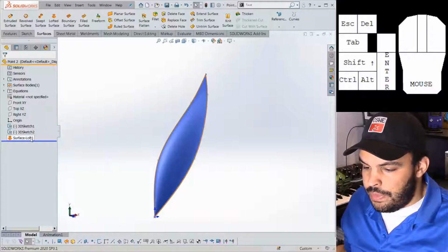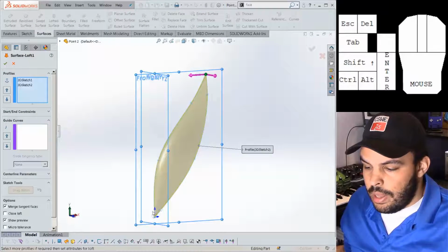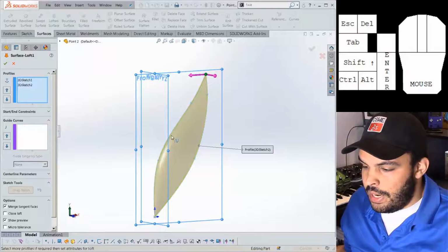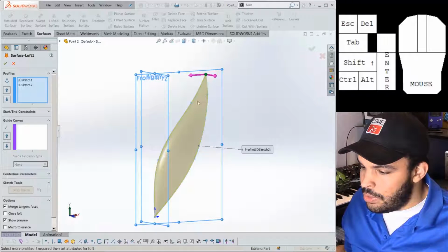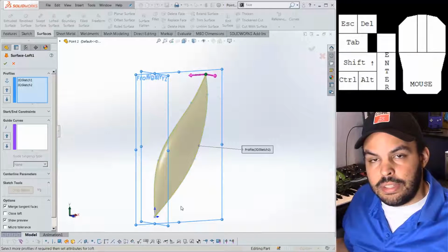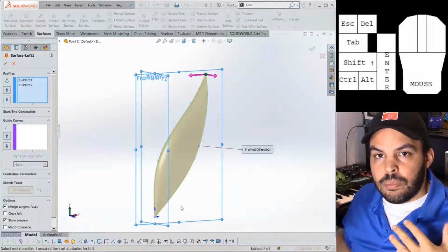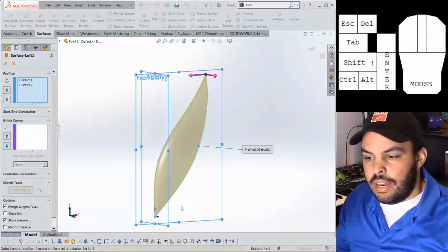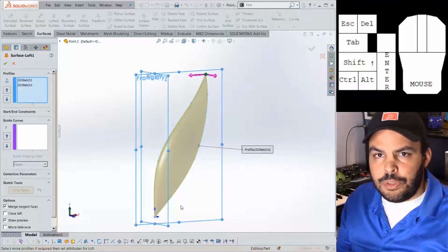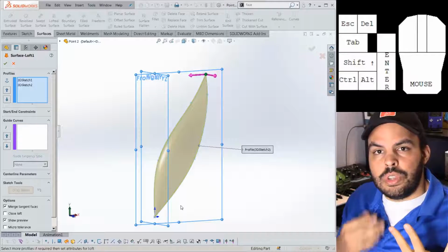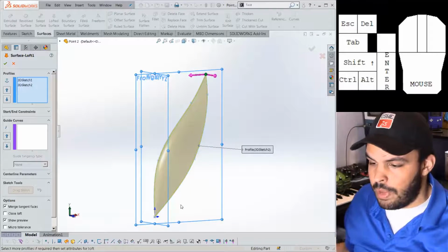So what happens if you use a loft on that, the loft still wants to be four-sided, but basically what happens is that it has two sides that have a non-zero length, and then two quote-unquote sides that have 0 length, or a point. So basically the rule of thumb is that loft and boundary, and swept surface to an extent, you want to use those for four-sided patches if you're trying to patch up a model.